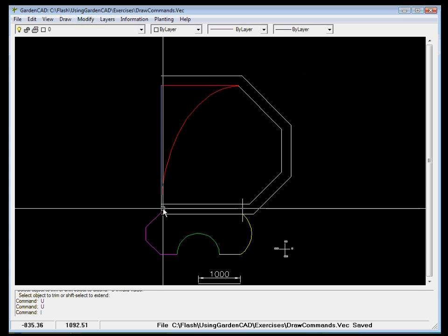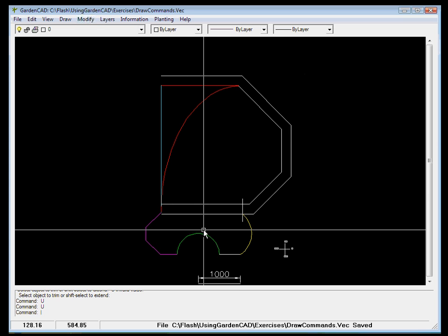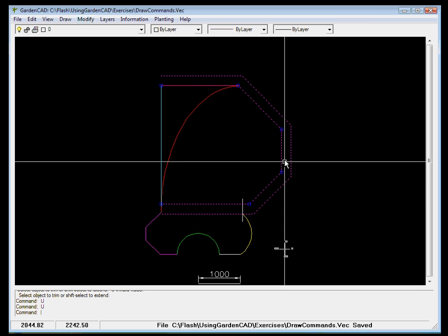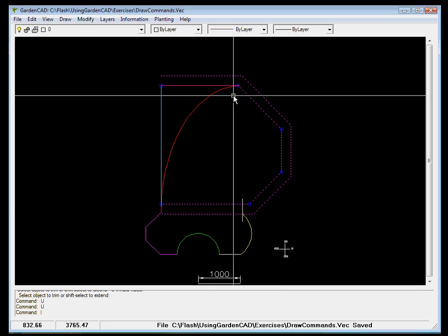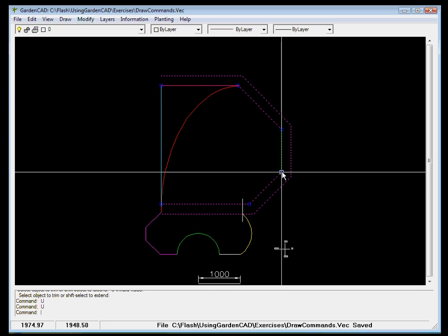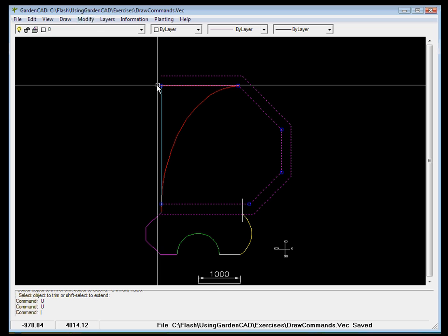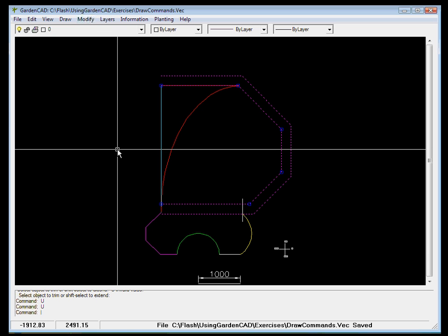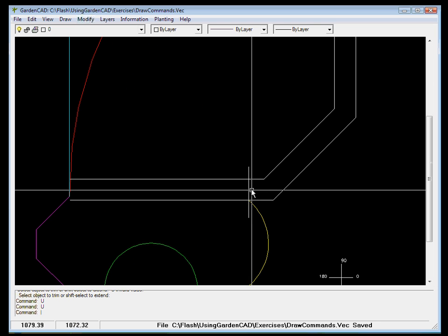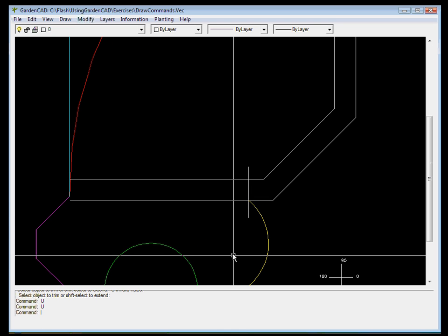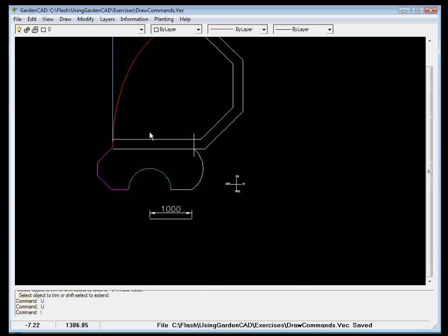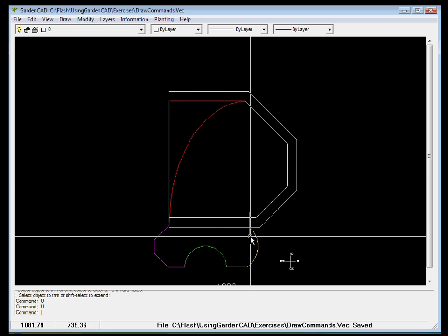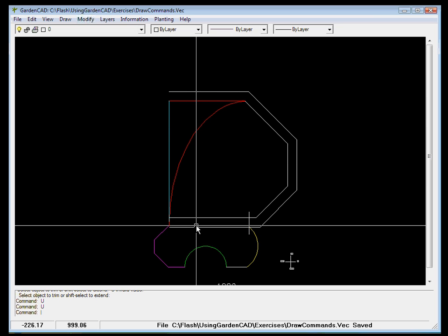Well, here's another opportunity then to have another look at the multi-line. If you click on the multi-line, you can see that it's one single entity, and these are the vertices of that entity, and that's being controlled by our multi-line settings, the one we've just been through. If we wanted to, as we would here, trim this off, so this would be our masonry wall, and this is part of our rather complex little mini courtyard that we're developing, we'd want to trim things across here to cut that section out.